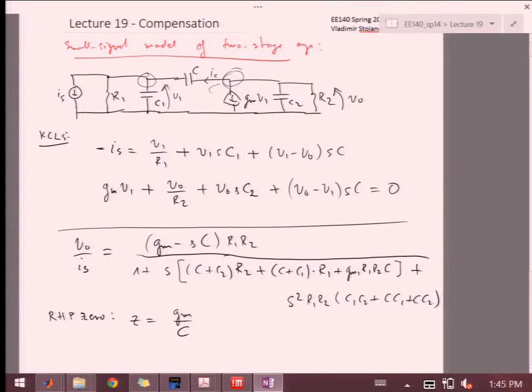So it will essentially feed the signal directly from the input to the output. It's kind of shorting the second stage completely. So there's no sign inversion. Normally, the second stage from base to collector or from gate to drain would have minus GM times whatever the load is, right? But here, the current will just shoot straight through, right? So the phase between gate and drain or body and collector will basically be 0, okay?